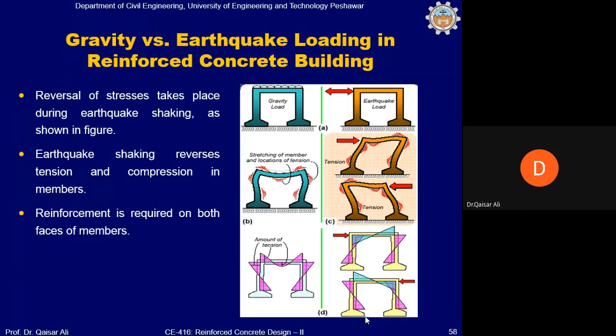Epoxy coated bars are used in situations where there is a high probability of corrosion due to exposure of the reinforcing bars, for example at the seaside, where sulfur dioxide and other detrimental elements or compounds exist in air, and they can attack concrete and thereby deteriorate it.